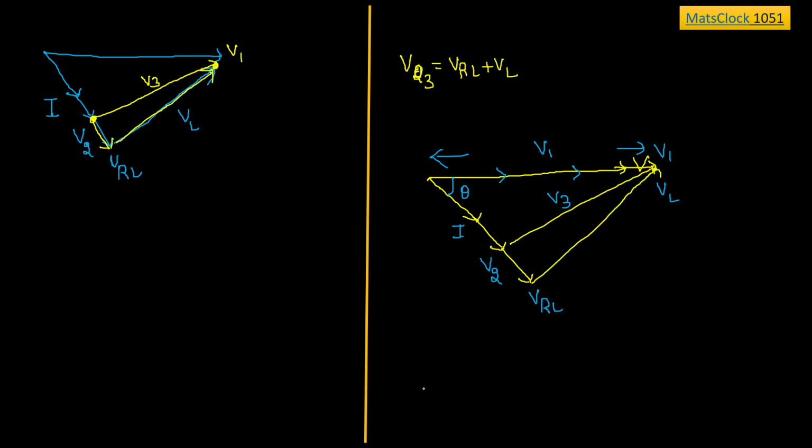Everything is fine sir. What are we going to do now further? I have given these many clues, right? Now use the triangles, formulas, anything that you want. I just wanted to know the phase angle value of theta. With the given data, the lengths of V1, V2, V3 are already given in the question, like 122, 136, 220. Now, how to write the overall expression, V1, in terms of V2, VRL, VL from this phasor? How will you do that?